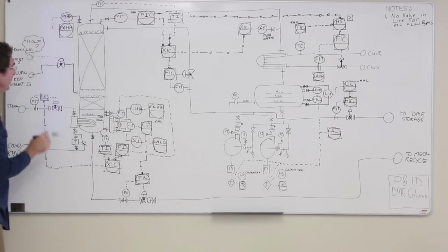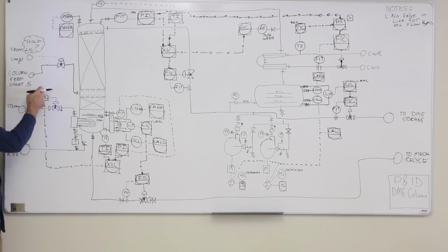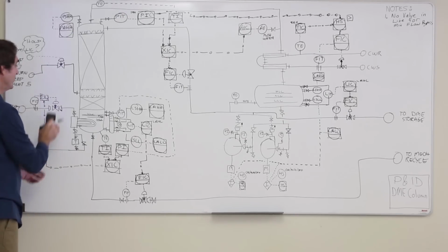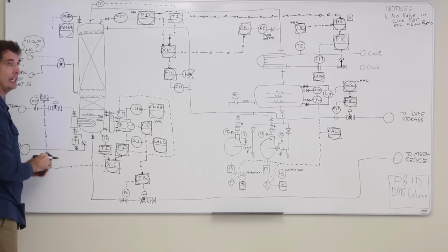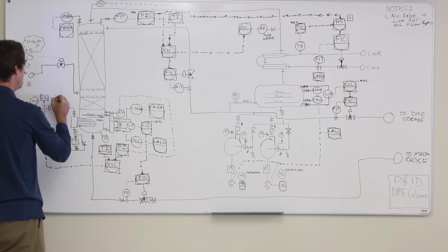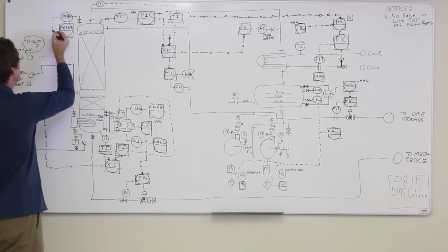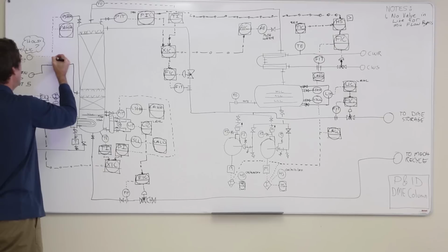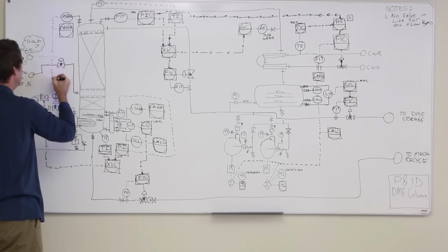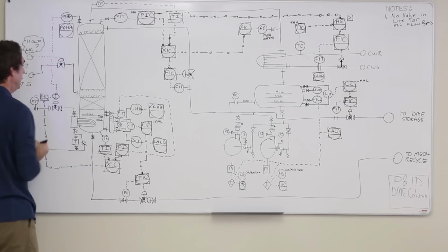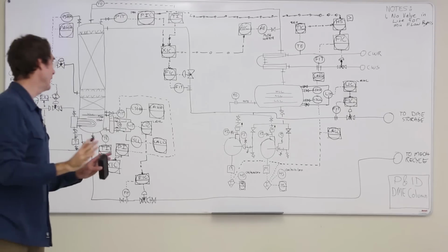And what I want to do is I could send a signal from the DCS from one controller to another controller, do it in software, or it's a fail-closed valve. I can just interrupt the electric signal. So I'm going to put an interlock in here, like that. And I'm just going to hardwire it into the valve.